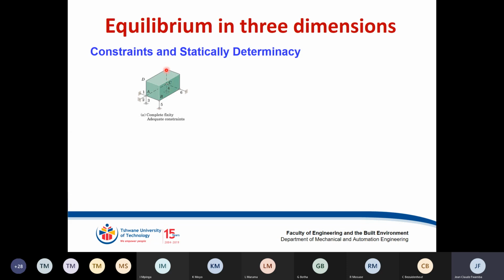Let's start with your Z axis. How many restrictions are being put there? There are about 3 of them, number 4, 3, and 5, which I believe will be sufficient to prevent any motion in the Z axis. In the Y axis, there are about 2 of them, number 1 and number 6, which I believe can do the job. X-axis, you've got about 1, which is number 2.